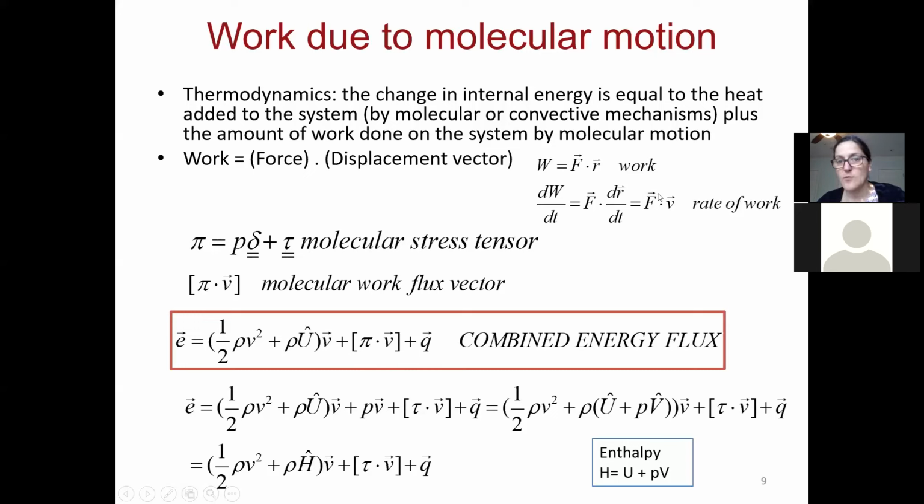So what used to be simple in mechanics, just a force moving a piece of something, like let's say I'm moving this cup, is not as simple anymore if I have fluids involved. Stress in this case is just the force per area of contact. Well, in fluids, I have to involve the stress tensor. So instead of just doing F dot V, I now have the stress tensor multiplying velocity.